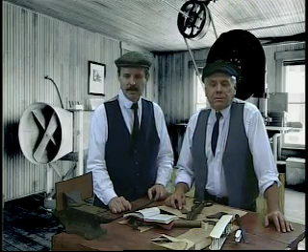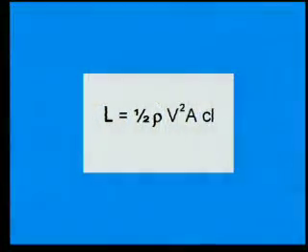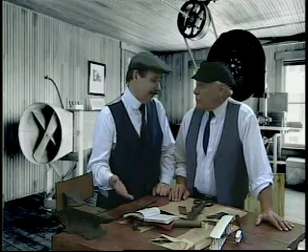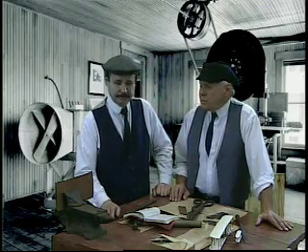We should also point out that the lift equation used by modern aerodynamicists, shown here, is slightly different. Smeaton's coefficient was a pressure factor, and more importantly, it's found that the density of air affects lift. So rho, 1/2 rho here, is used for the density of air. And you can see why modern airplanes, when they go higher in altitude, have to fly faster, because they make up for less density. We were flying at sea level, so this wasn't a factor.